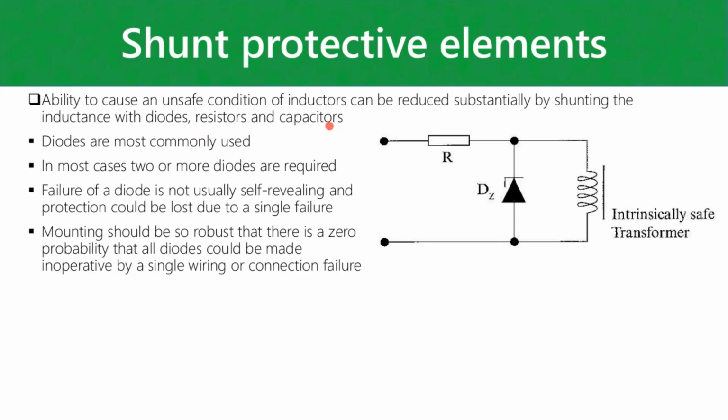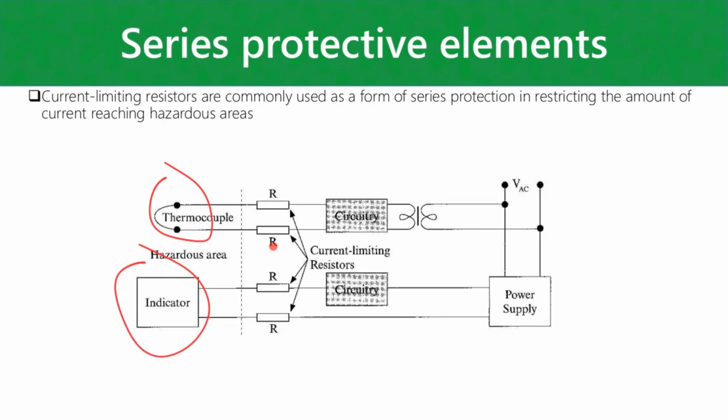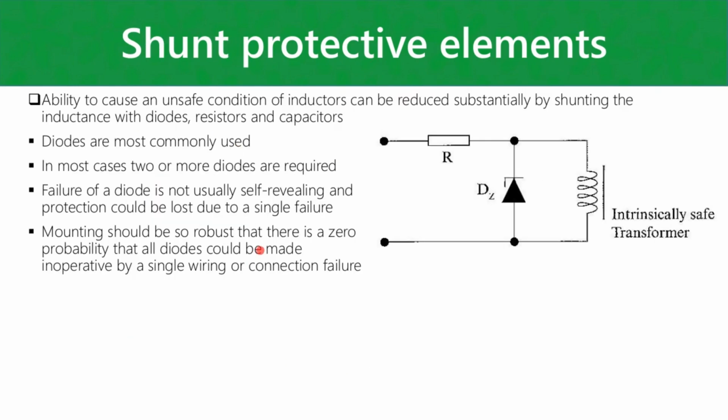Then there's also, so we're actually looking at shunt protectors. So this is series protective devices, shunt protective devices. Shunt protective devices, something that is most commonly used in this role are diodes, specifically things like flyback diodes.